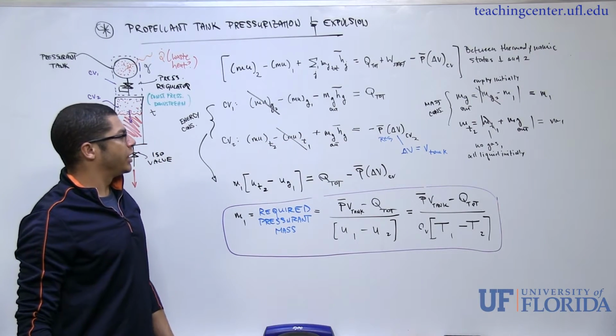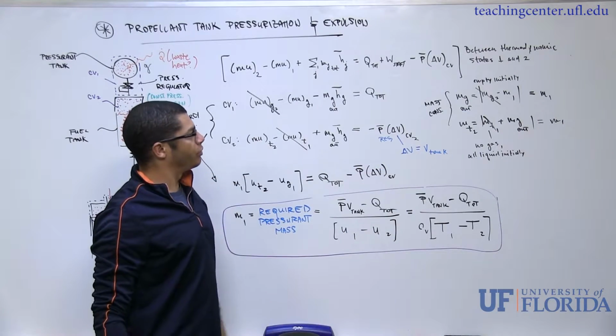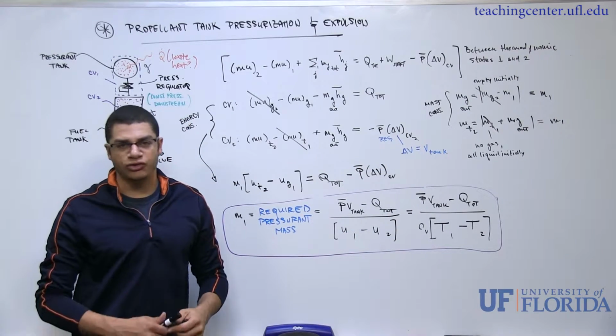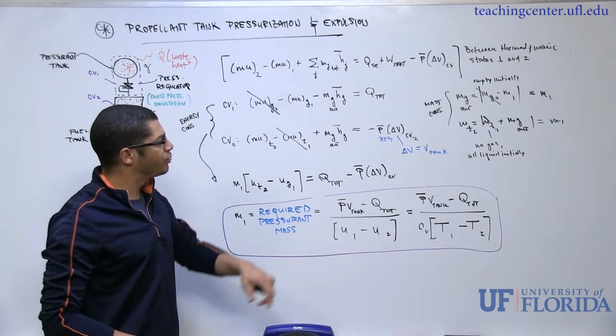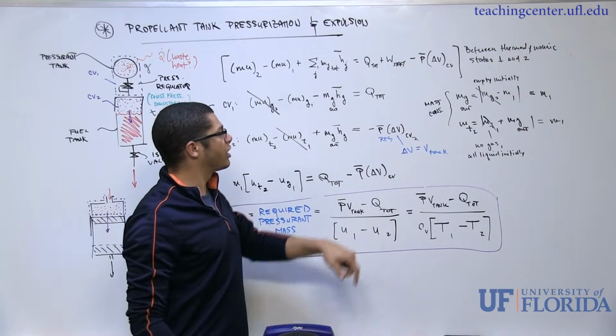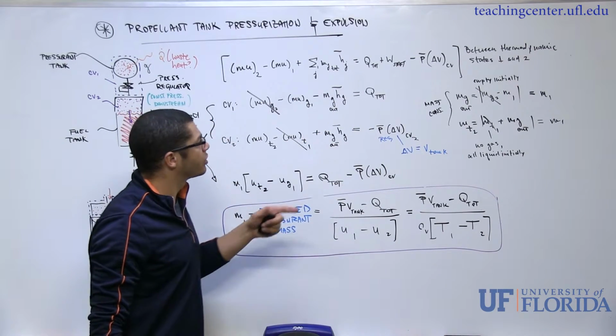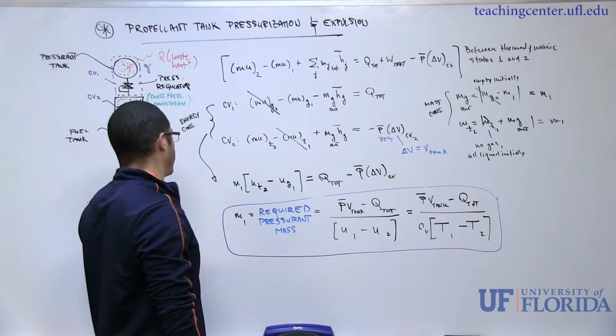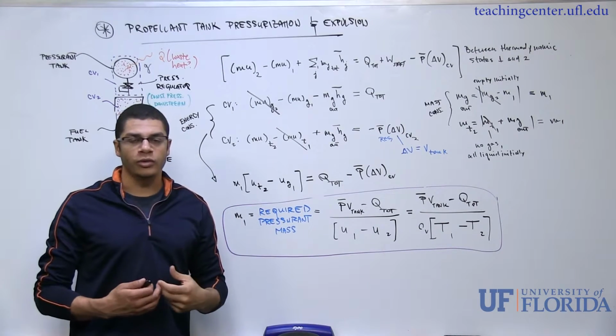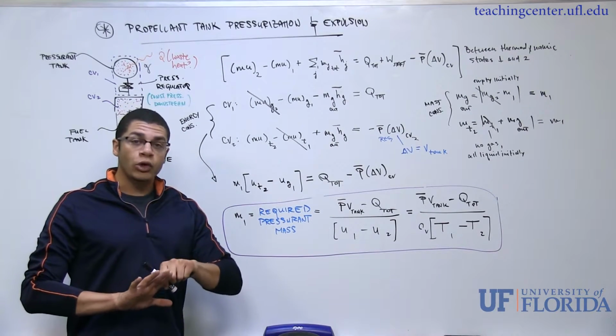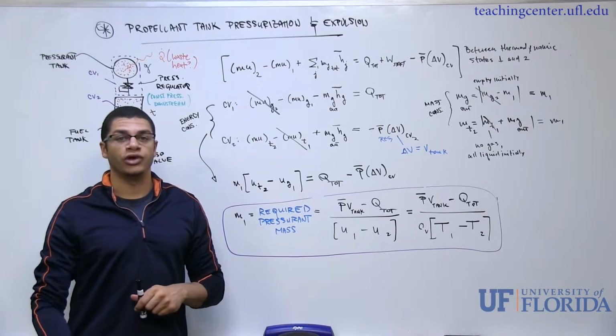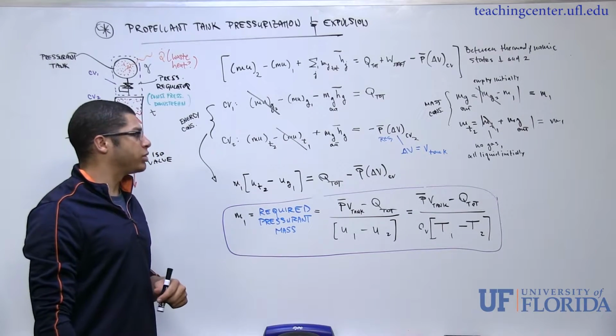On the right-hand side over here, we neglected the possibility of heat transfer, although it depends on the application. No shaft work, not for this particular configuration. But because our bottom boundary is moving and the control volume is deformable, the gas is doing work on the liquid downstream and whatever resistance may be placed on the liquid.